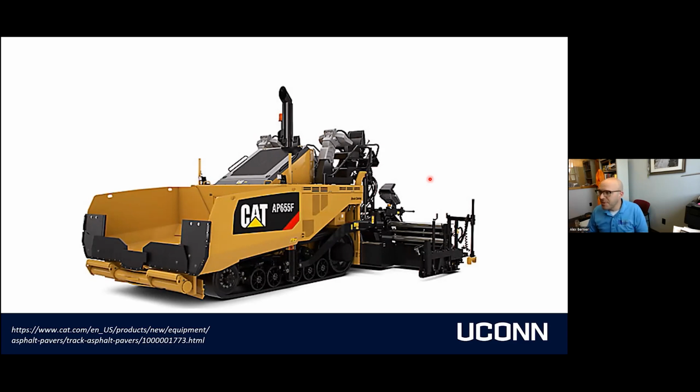So this is a picture of a pretty modern paver here. And we're going to go over some of the parts. The first one is the hopper. This is where material enters the paver from a haul unit, or you have an insert for an MTV. But the idea is it's built to receive material. There are actually slat conveyors down in the bottom that are going to drag material back through the paver. Slats or rakes, those are the conveyors.